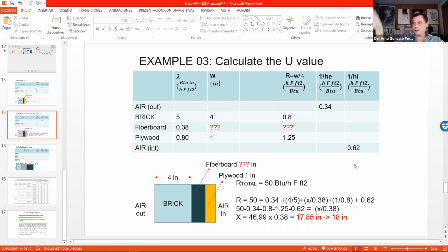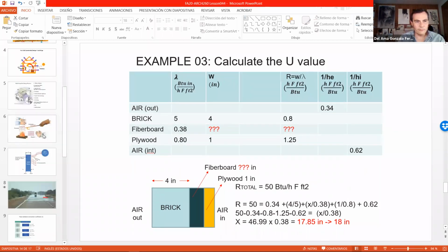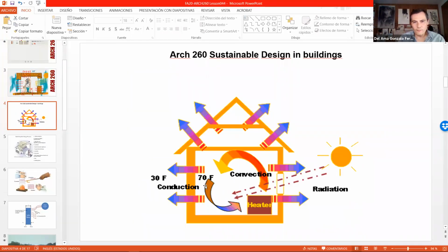Then you can add internal finish or external finish, so you end up having a huge wall. So you have to get used to that. When we are designing, walls have to be thicker. And southern walls maybe can be thinner than northern walls, as we can see in this picture, because this is thinner than that.